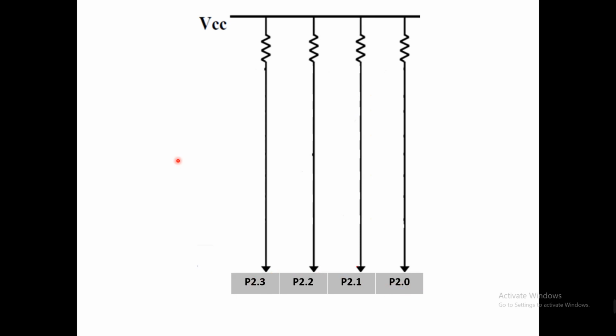Okay. So what will be the value at this point if you want to read the value at this area? What do you suggest? Will it be 0 here or will it be 1? It will not be 0. It will be 1. Why will it be 1? Because this point is directly connected with the plus VCC. So this is one value, and the same is for this one. So all these values will be 1, 1, 1, 1 when we connect the four wires with the supply.